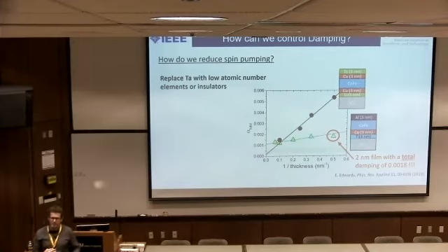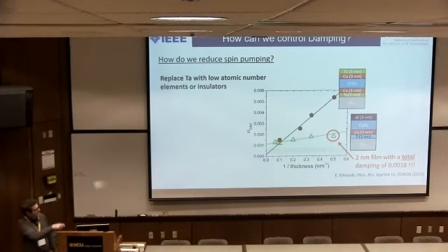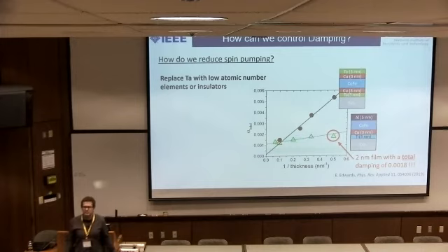And so it's all about, I don't know if I'm doing a good job of answering your question or not, but certainly the intrinsic damping is material dependent. The total damping is, of course, even depending on spin pumping contributions, such as what it's in contact with. As we can see, we can vary that very dramatically in this particular case by changing the other layers in the stack. So there is no one damping parameter that can be used. So that was a very long-winded way of answering your question, maybe, but yeah.